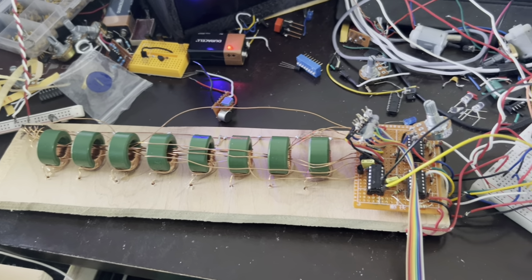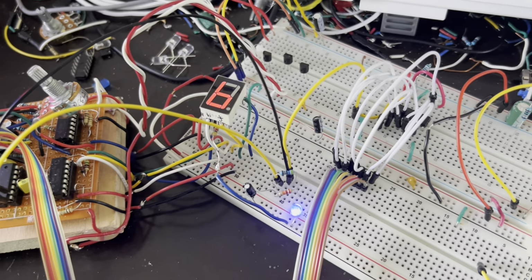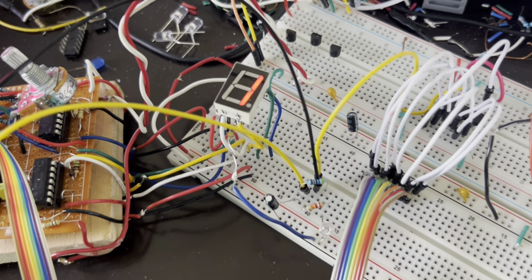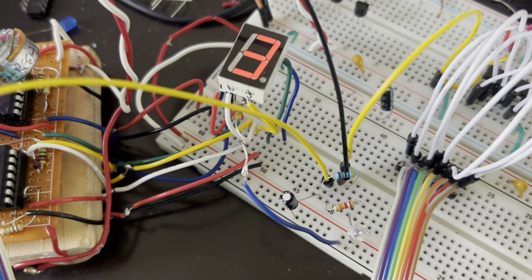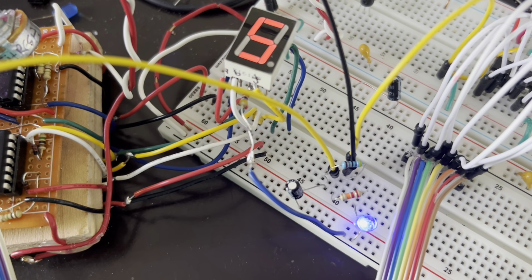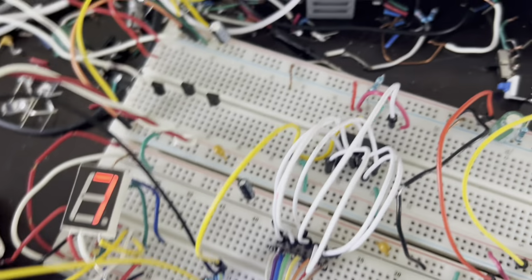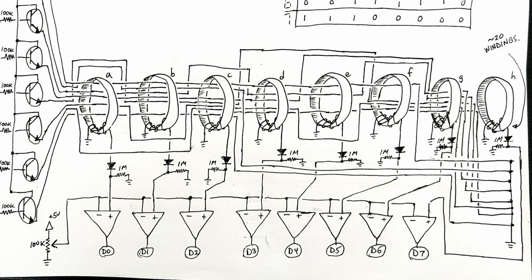So now I've attached a low frequency oscillator to be the clocking signal for the CD4017 timer. And here it is in an automated way, just counting away. And once again, I reversed the count. So in this way, the core rope memory works in any way you set it, but it's hardwired. And so I will leave you guys, as always, with the schematic of this particular circuit.